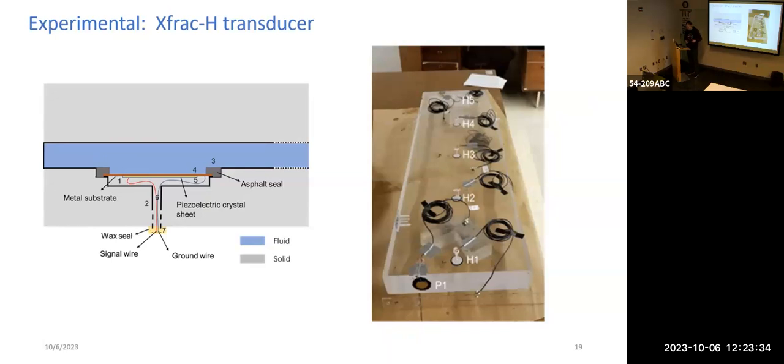The answer is that we set up the airbag, the air cavity, which means we can excite the flexural mode of the PZT film. The flexural mode works at a much lower frequency, so the flexural mode can be used to detect the low frequency vibration. I will show the waveform recorded by the PZT in the next slide.